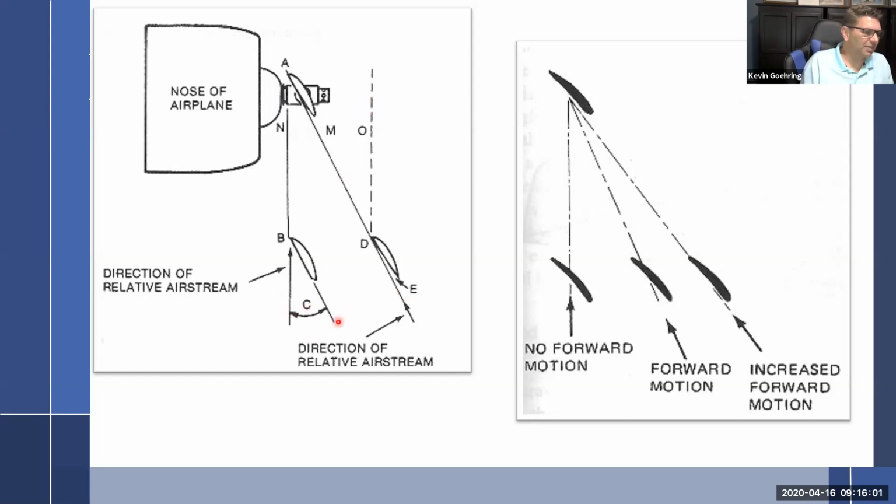Yeah, extraneous. I don't need to talk about it. We already covered this. I don't need to bore you with it. I also wrote in a dive or a climb. Well, of course, if we start to climb or start to dive, that changes everything too. So in an extremely steep dive with high speed, the prop doesn't really know that it's in a dive. All it knows is angle of attack, and the angle of attack is based upon speed and RPM.